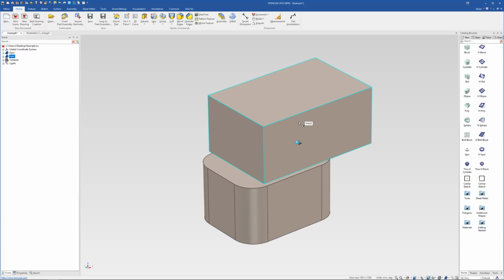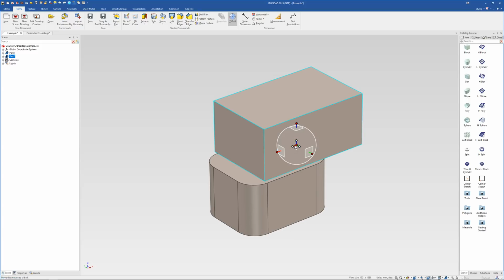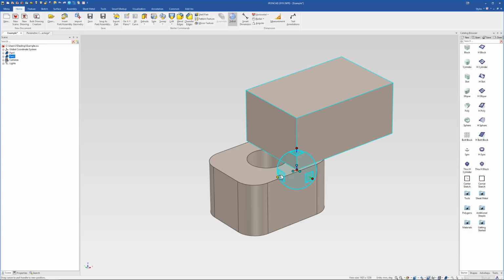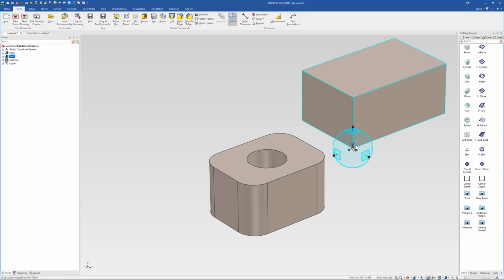Sometimes when you're sizing a complex shape or positioning it, which I'll show you in a second with the triad, it's much easier to find it like that. So you can see here, if we want to move via this corner with the triad, let's just move this out into space a little bit. If we were just dragging on this edge here, we can find the midpoint there. It's not too much of a problem.